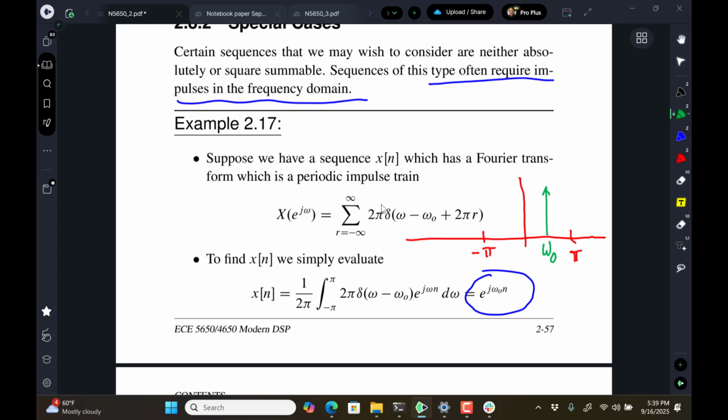So we just focus on the interval minus pi to plus pi, and then we're good. But the delta function doesn't replicate itself, whereas something that's a function of e to the j omega is automatically a mod 2 pi function. Remember, I pointed that out quite a while back tonight. The delta function doesn't have that property, so in order to make it a periodic spectrum, the sum has to be put on there, and it makes it look very messy, and we'll bump into that in another example tonight.